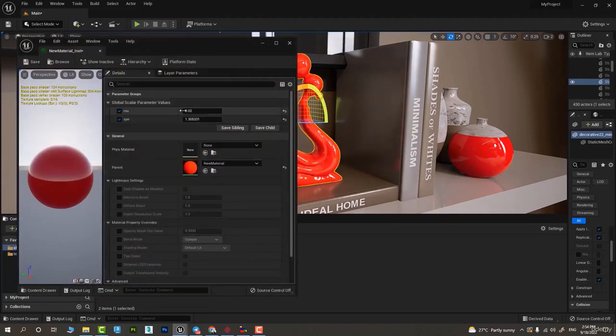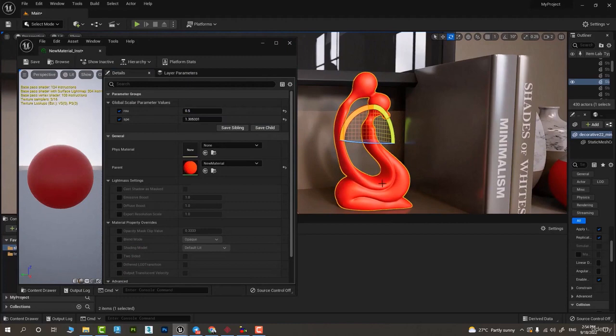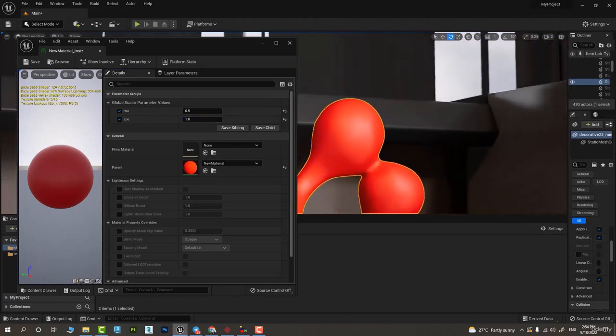Okay, I'll double click on it, go to roughness, choose a bigger value, maybe 0.5 to see the effects of the specular better. So right now the specular is at 1. You can see some glowy light effects on the object. If I make it smaller, you can see less of that. So the more I increase the specular from 0 to 1, the more we will be able to see these light particles or light glowy effects on our objects.